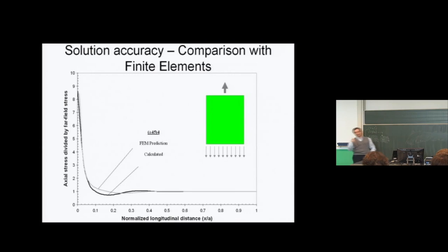So this is an indication of the kind of reinforcement you would need. There's no point in reinforcing from here on, which would correspond to some point in the middle of the plate and moving towards the bottom end, because the stress there has already reached the far field stress. So that's the one that you would design for anyway, and there's no point in reinforcing there. But there is definitely a reason to reinforce from 0 to about 0.3 or so, at least for this specific laminate and for this stress. Remember, there's a whole bunch of stresses. There's a sigma y and tau xy stress that we also have to double check.